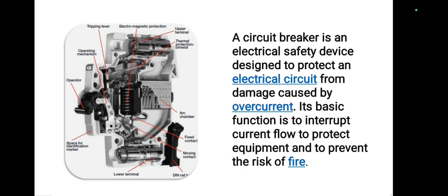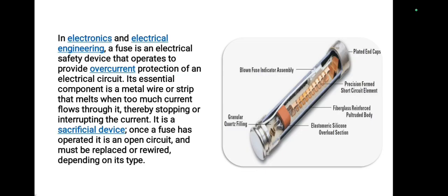Now move to the fuse. In electronics and electrical engineering, a fuse is an electrical safety device that operates to provide overcurrent protection of an electrical circuit. Its essential component is a metal wire or strip that melts when too much current flows through it, thereby stopping or interrupting the current. It is a sacrificial device. Once a fuse is operated, it is an open circuit and must be replaced or rewired depending on its type.